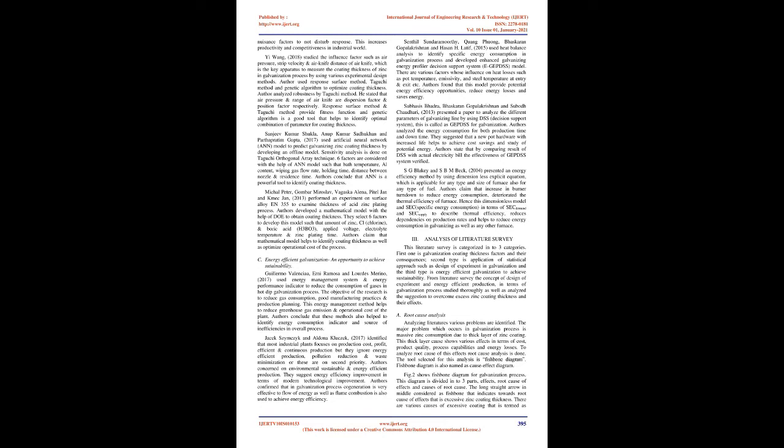Pengbiko, Wang Jianhua, Susuping, Liji, and Yinfukan, 2007, carried out an experiment to study the influence of zinc bath temperature on the coating thickness of the galvanization process. Authors used a pure iron sample, with bath temperature ranging between 450 and 500. Immersion time was 1, 2, 3, 5, and 8 minutes. SEM and EDS methods were used to analyze the coating thickness of the sample. Authors conclude that at 480, the coating grows at the fastest rate at the same immersion time.